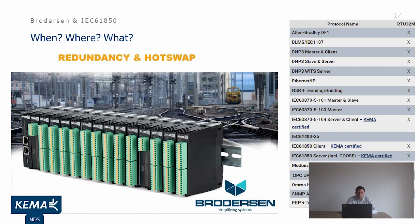Another common scenario is also in new installations, but here the RTU is acting as a data concentrator because it collects data directly from many IEDs using IEC 61850 or 60870.